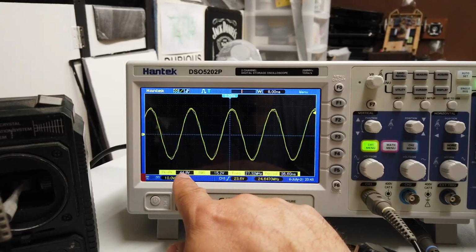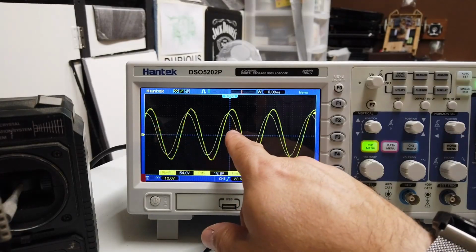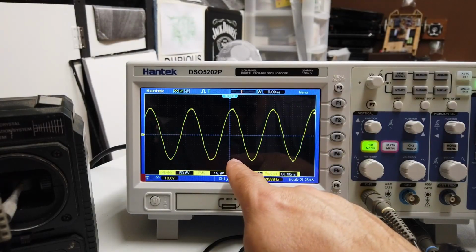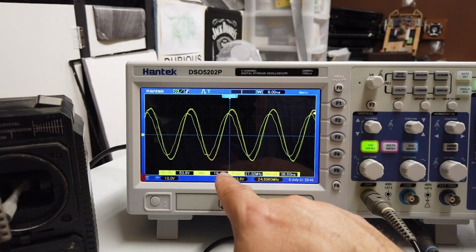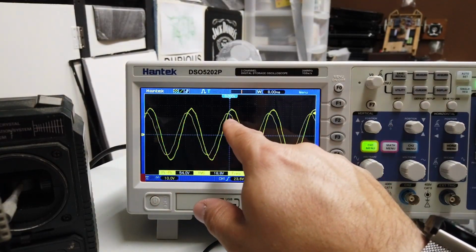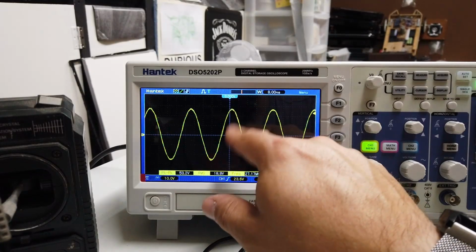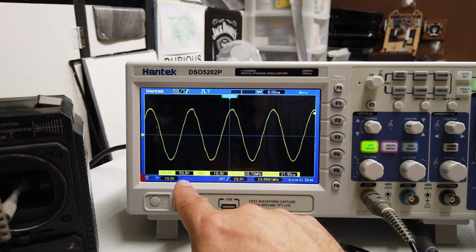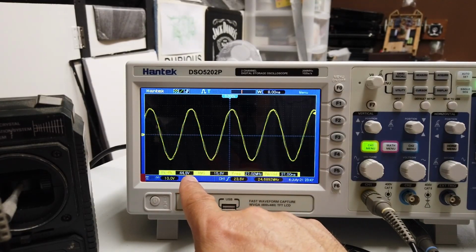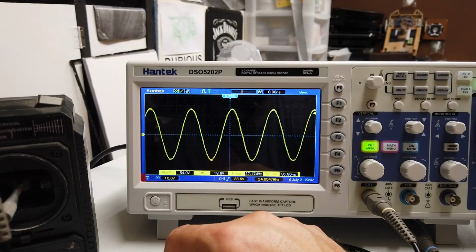And not only that, but if you look at the peak-to-peak voltage, if you look at the number of graticules, the divisions here for the amplitude of the wave. Currently, you'll notice we are set to 10 volts per division, indicated just here. And so with 10, 20, 30, 40, 50, 60, around 60. And it's sort of waving up and down a little bit. And the scope itself is now giving us an idea of the voltage. It's saying it's about 54 volts peak to peak. Again, that's a really nice little feature to have.